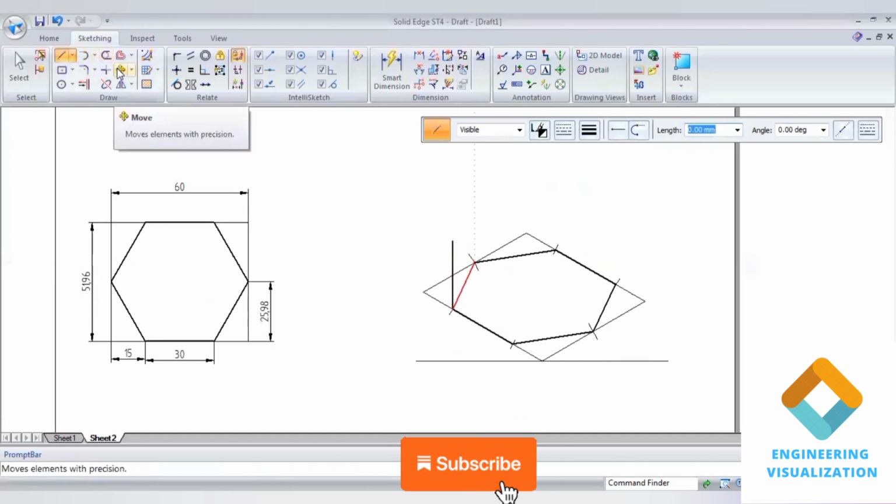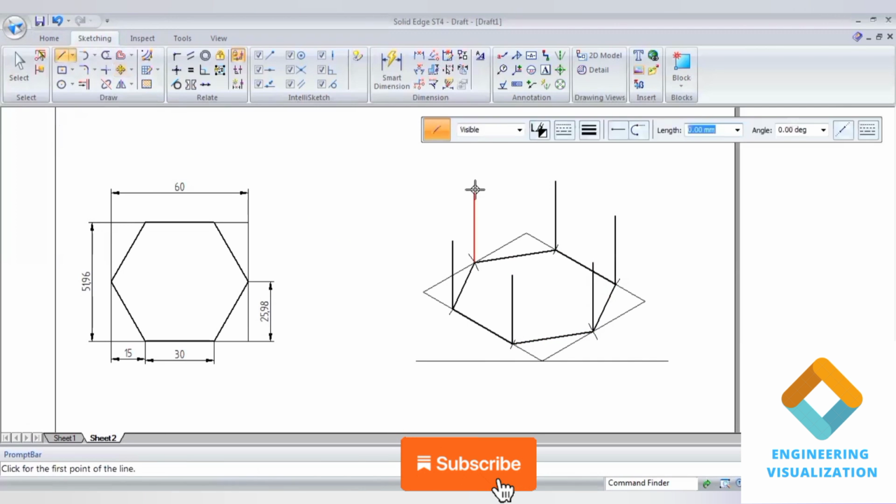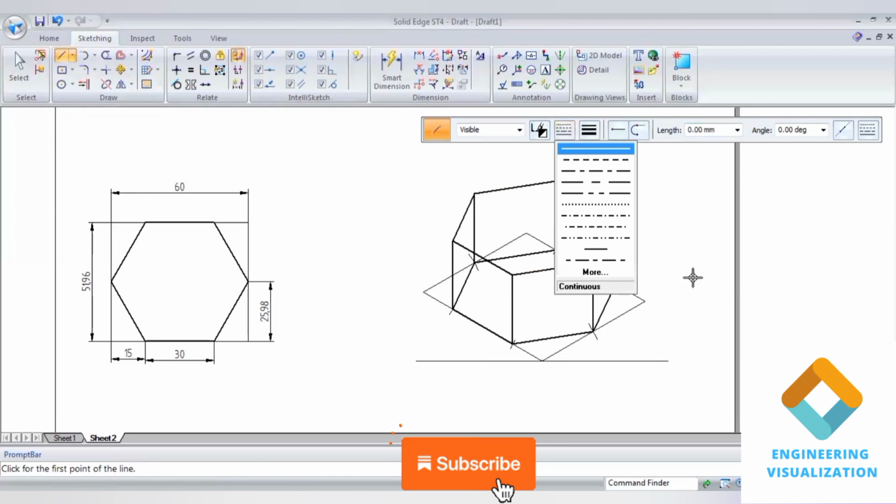Okay, we go to the move command. It's a copy. Select the corner end and then place it with respect to all the corner points. Okay, by using continuous line, I want to join all these corner points. So that completes the hexagon. Now exactly at the center of it we have to place the cone here.